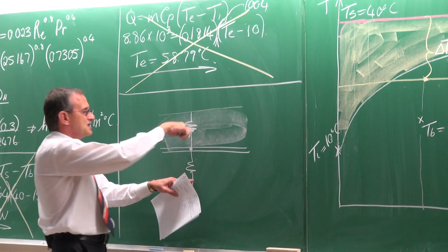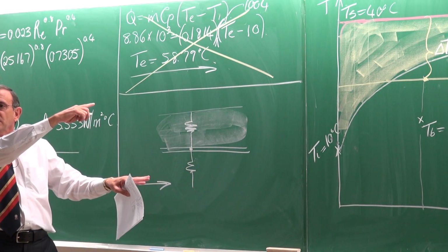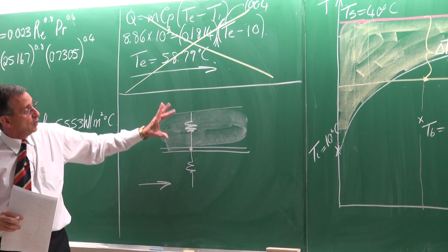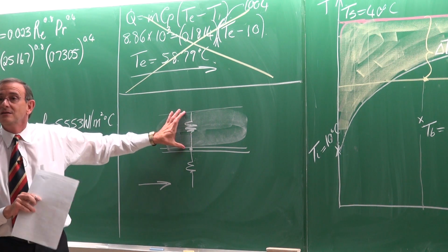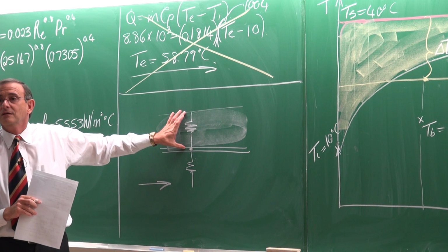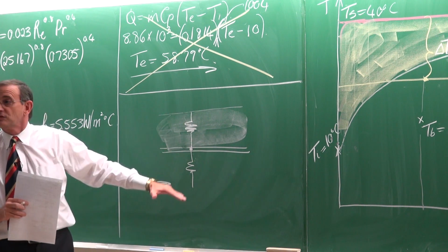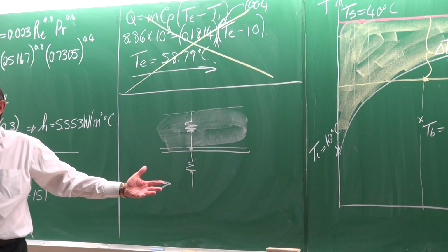These three resistance terms will determine the heat transfer rate. So, if you put insulation there, you want this resistance term to be very, very high. Because if the resistance is very high, then there can be no heat transfer through it. And that is the idea.